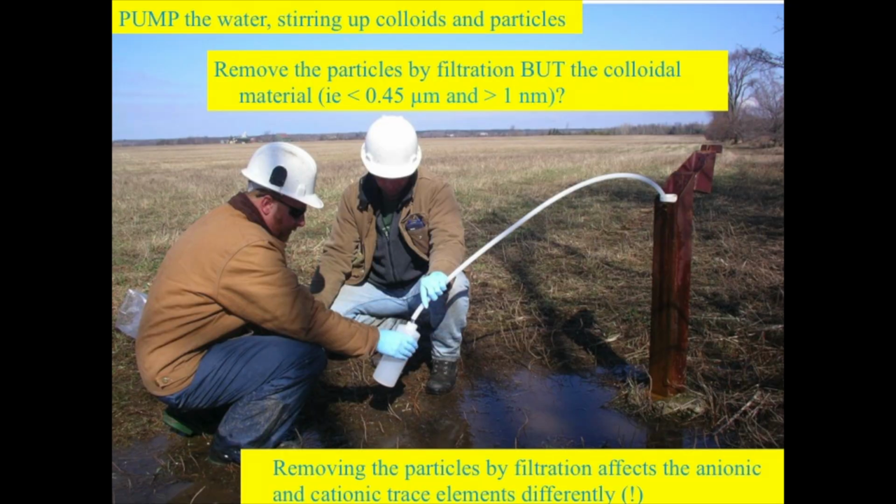So first of all, they pump the water from the aquifer, which stirs up the particles. It stirs up the sediment. It stirs up the colloids. And then they let the water run clear, watching it with their eyes to determine when it's clear, and then they filter the water.